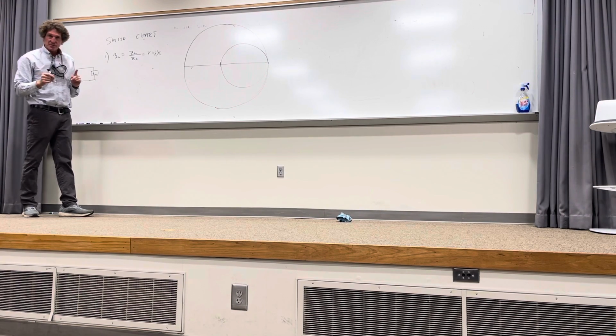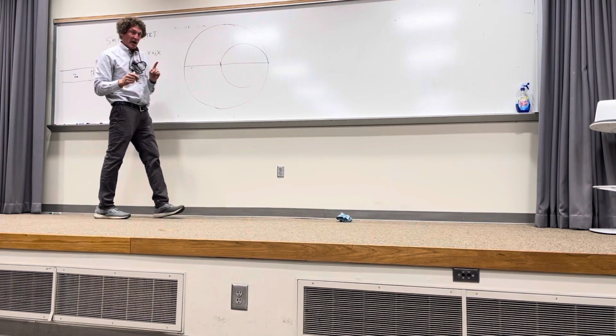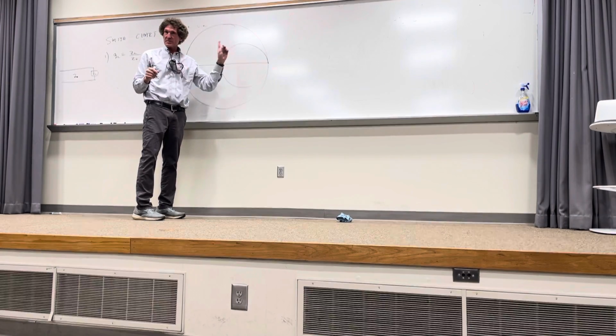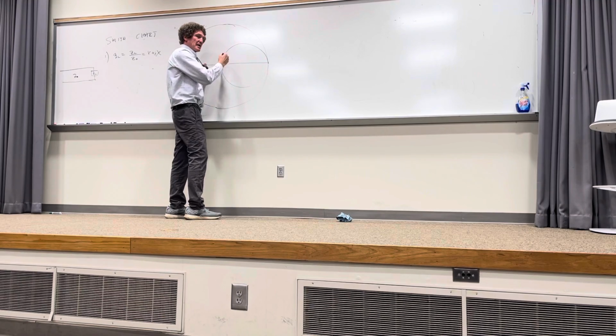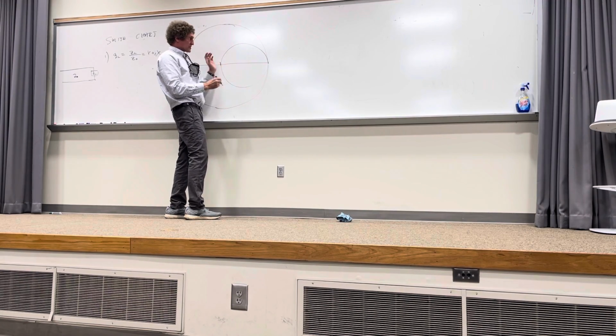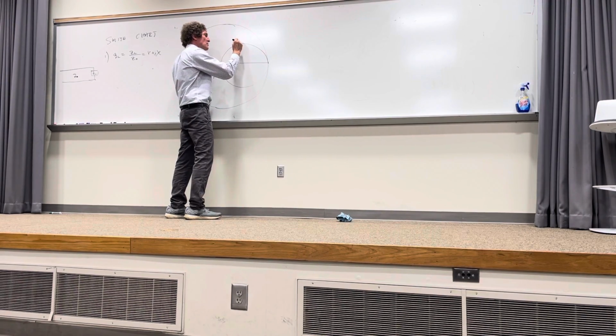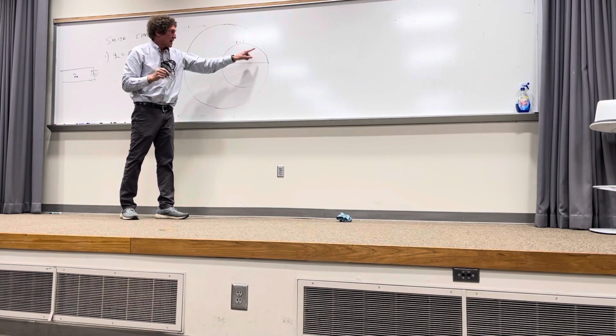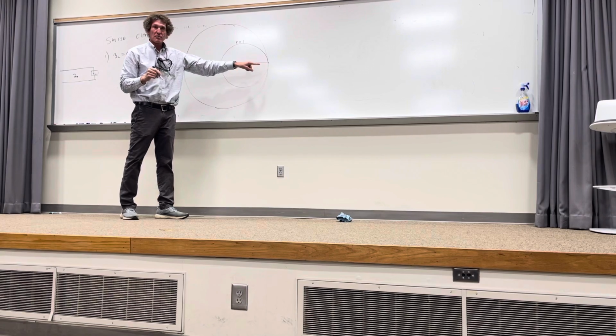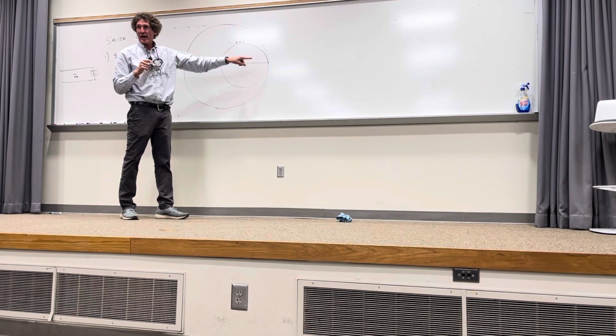You can look on your Smith chart in a second. So how do we go about finding that in this crazy thing? Well, this circle I drew here, that goes right through the center, is called the R equals 1 circle. It represents the entire range that R equal 1 normalization for that ZL could have. Y'all following?